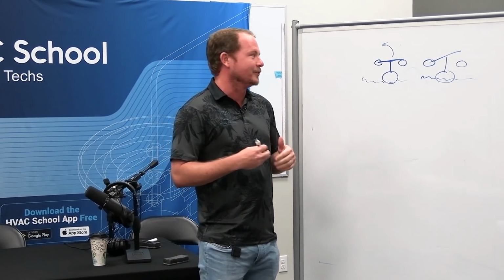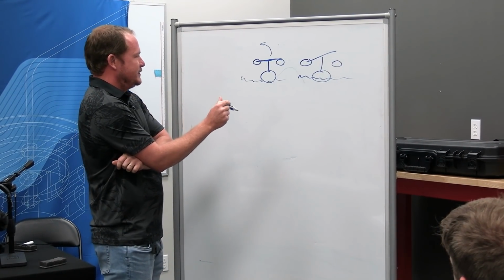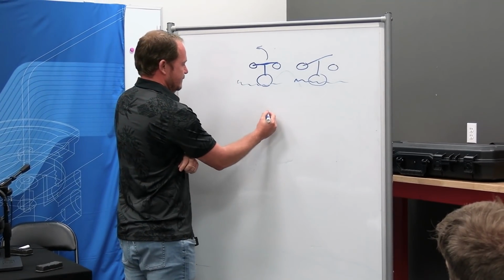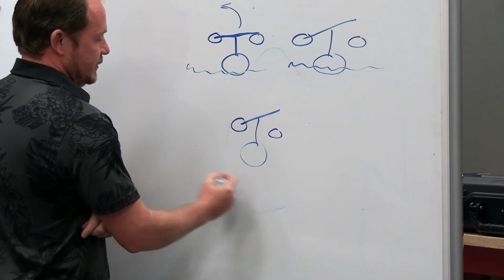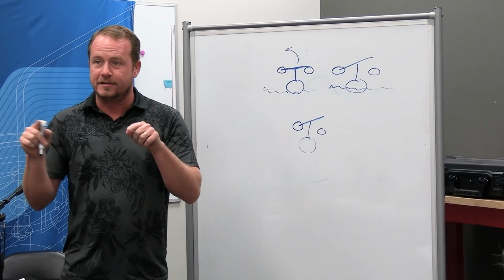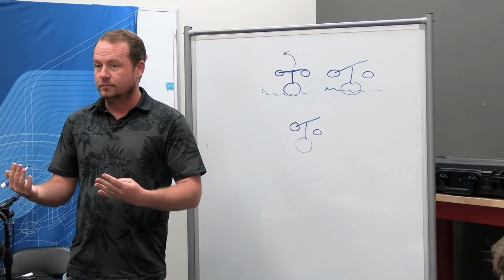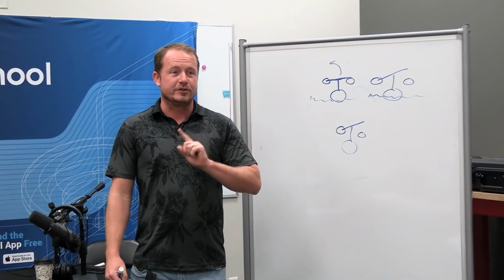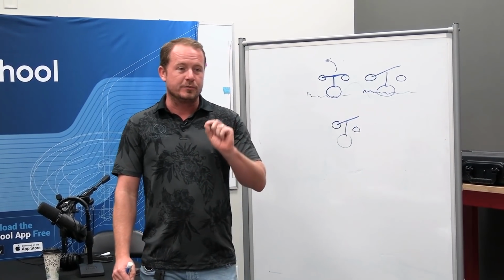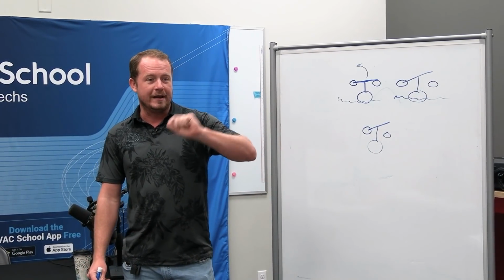I generally call them my children, but anyway, if you come up to a float switch and there is no water in it, and the float switch is open, right? So it's here, there's no water. You check with an ohmmeter, it's not ringing out, there's no path. What would you do? You'd say it's a failed switch, right? But here's the trick to this question. If the switch is failed open, what likely happened when it failed open?